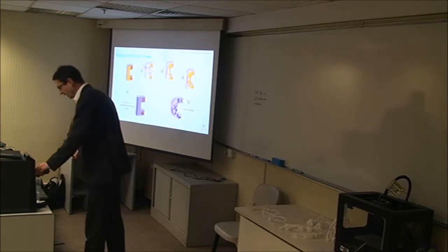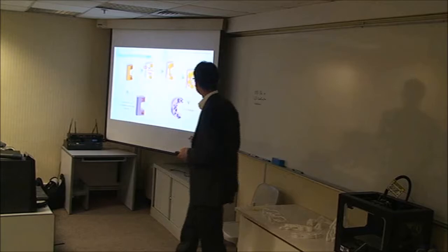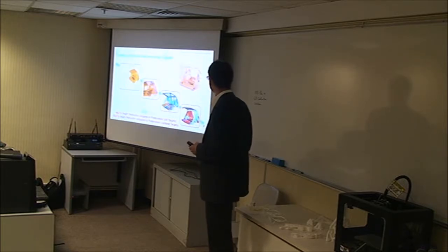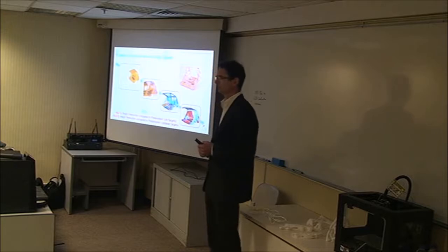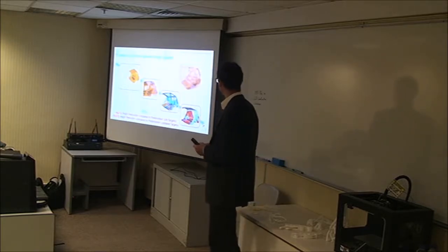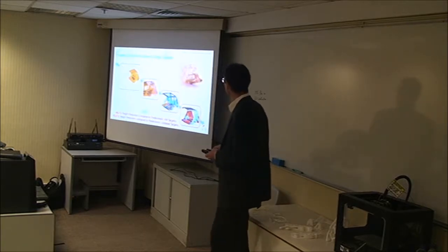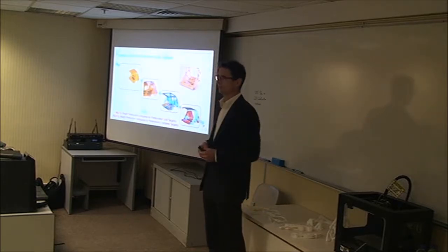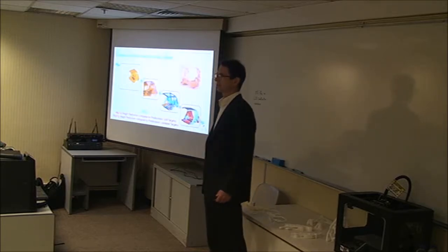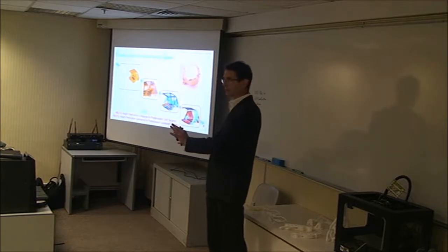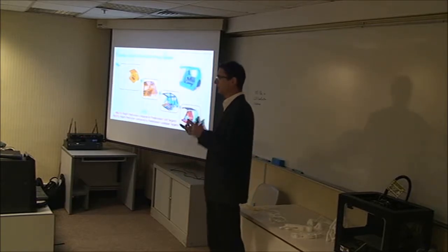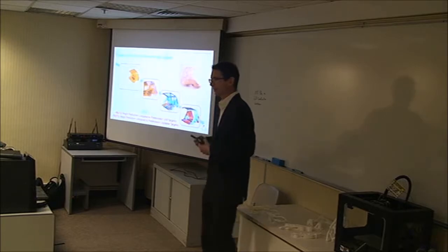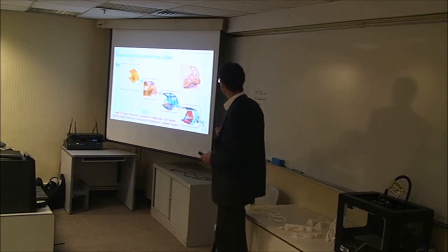You do that not only for a simple part, you can do that for a full vehicle as well. It's a study that we did some years ago with Opel. At that time it was General Motors, now it is Peugeot who owns that knowledge. So we defined the full rear end of the vehicle as a design space, and told the computer, that's your job, do whatever you want. Of course, we defined the attachment points of the suspension and the crash loads. We had to define where the passengers are sitting, and then we got a design out of it.